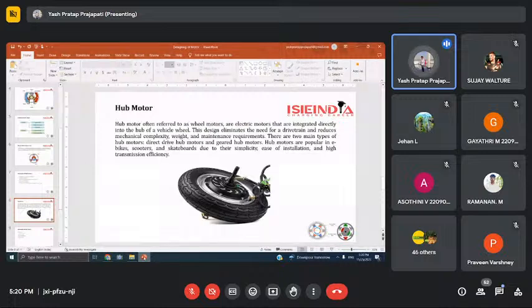Getting rid of the brushes also saves having to replace them every so often, as friction wears them down. In an ordinary motor, you'd expect the inner coil to rotate. It's called the rotor, and the outer magnet to stay static. That's called the stator. But in this motor, the roles are reversed. The inner part with the coil stays static, and the gray magnet spins around it. Now look inside, and you can see exactly how it works.